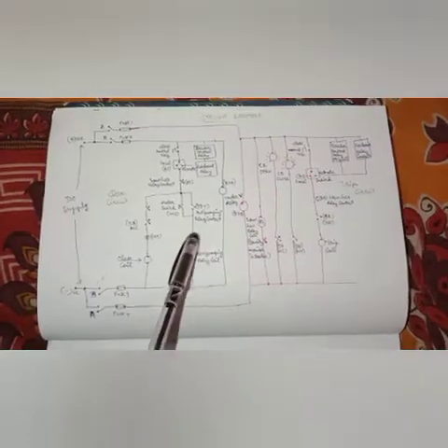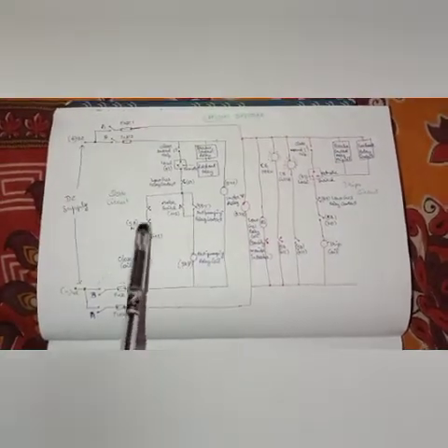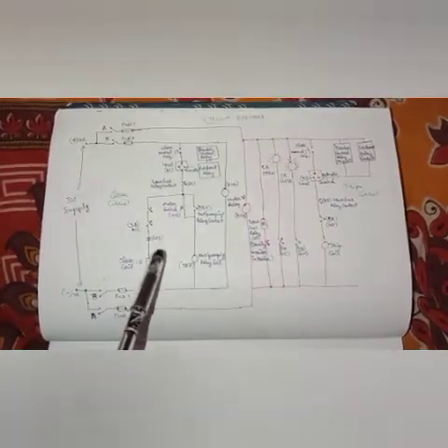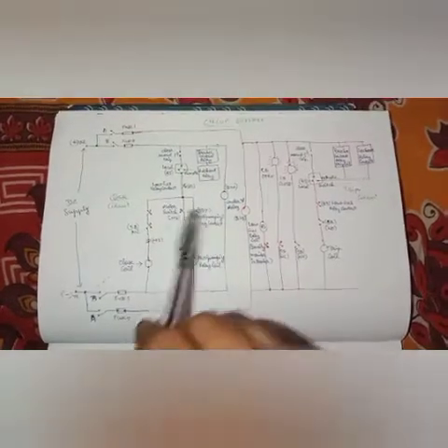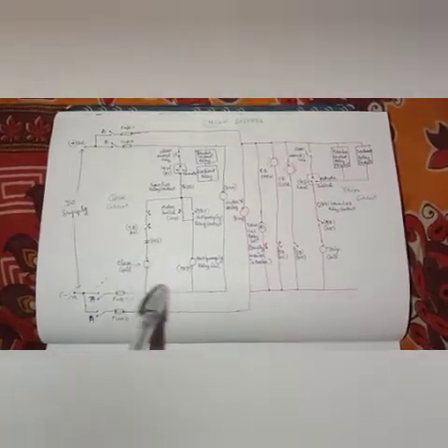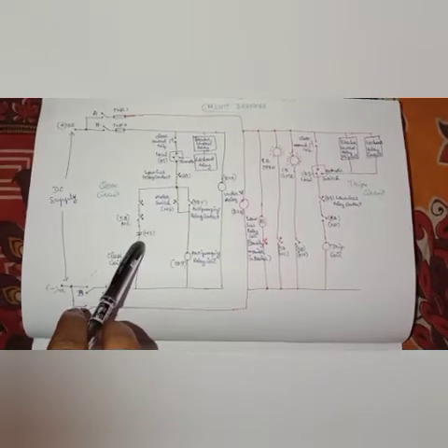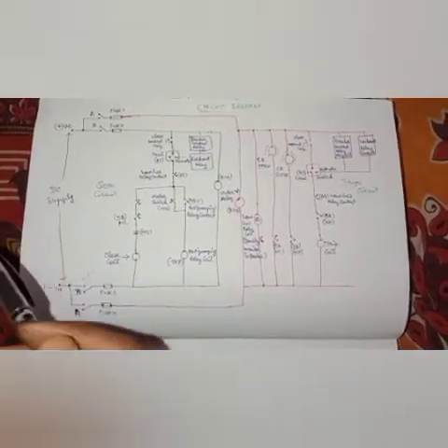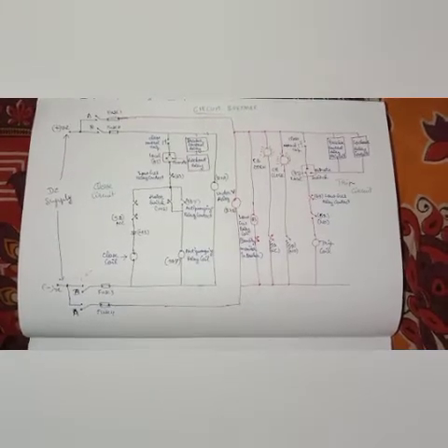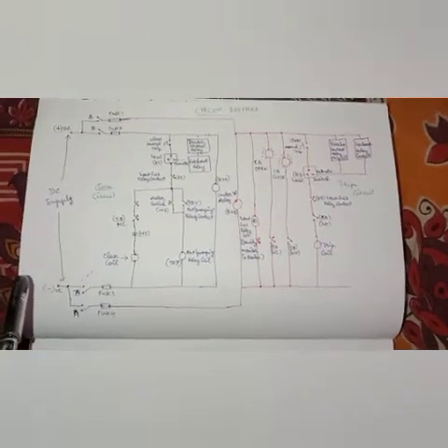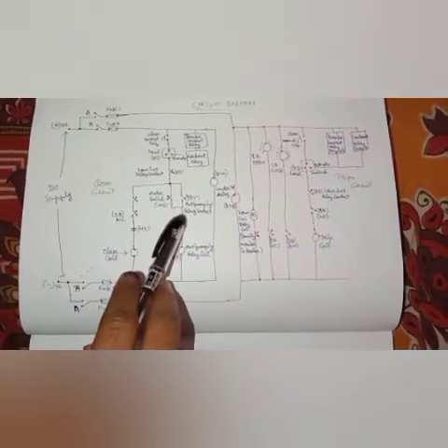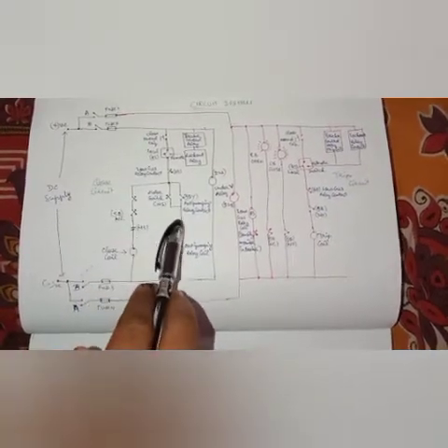So here the anti-pumping relay circuit is connected parallel to the close coil contacts, because once the breaker is closed, the positive should not feed to your closing circuit again, because the coil would get damaged. And also the closing and tripping should be initiated by spring charging of your circuits, and the spring charging also needs some time. So in order to overcome this, we are adding a separate anti-pumping relay circuit in parallel to the closing circuit.